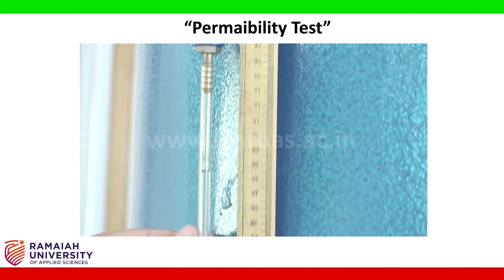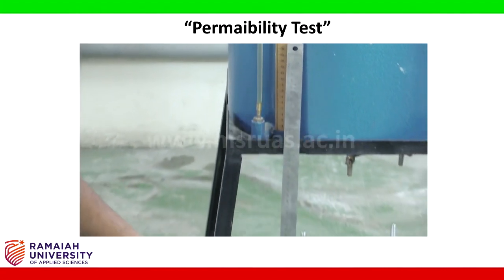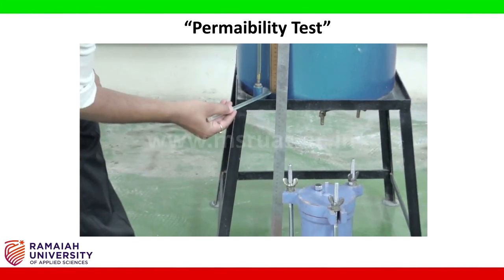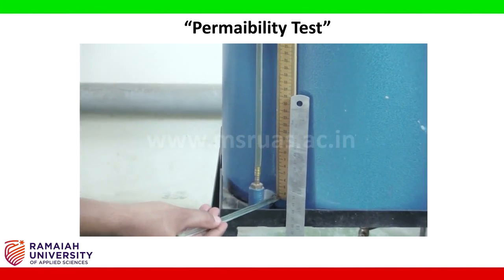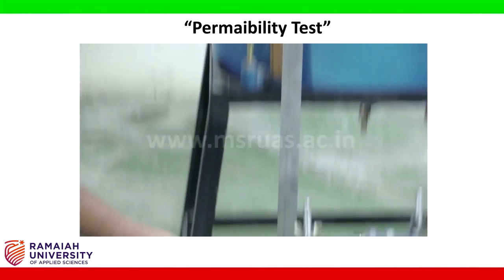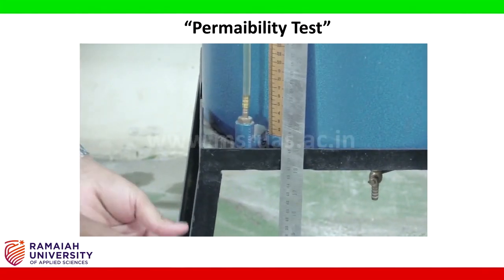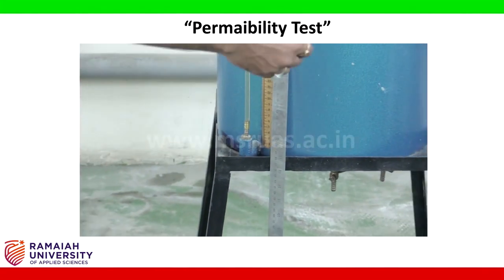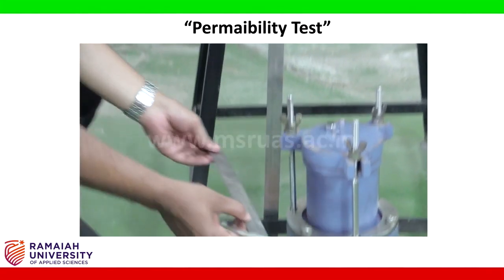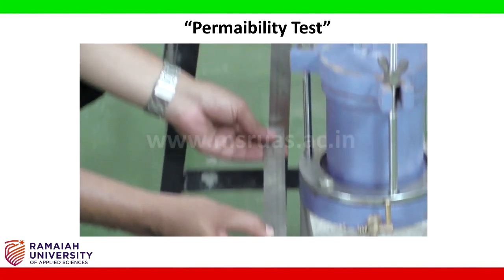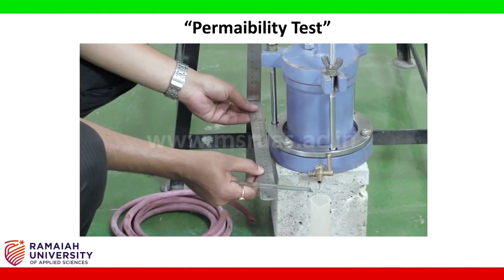We can make use of the steel scale to have an excessive measurement above the limit of the scale which is placed with the reservoir. For that, place a metal scale in level with the reservoir. Take one more steel scale and measure the total height with respect to the center of this exit tube.